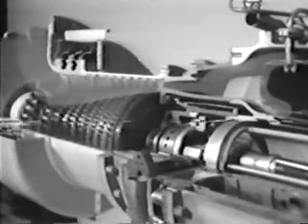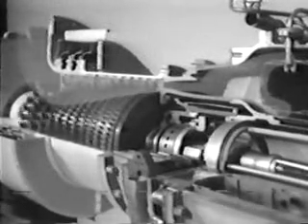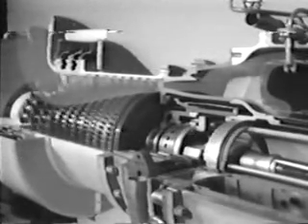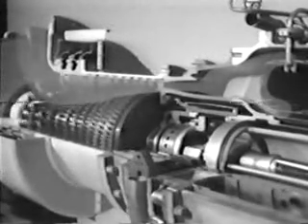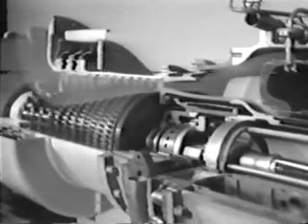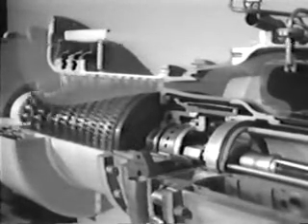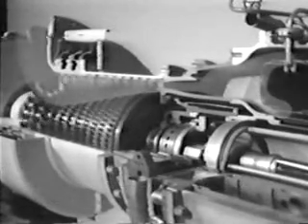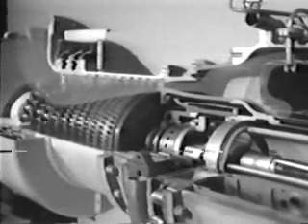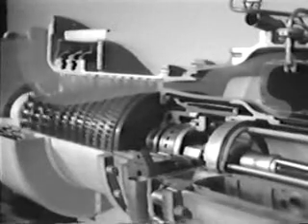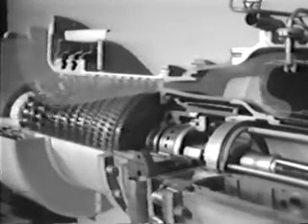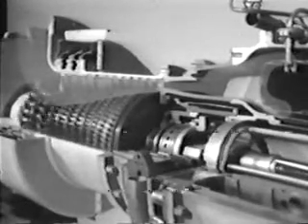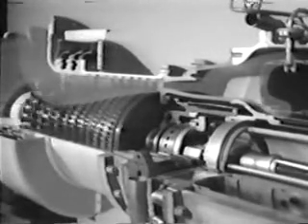The compression of the air plays an important role in producing power. The design of the compressor permits large quantities of air to be compressed into an exceedingly small volume, both to sustain and cool combustion. Diffusion, the key to compression, occurs throughout the compressor. The result is the delivery of high-pressure air to the combustor without any significant loss in airflow velocity.